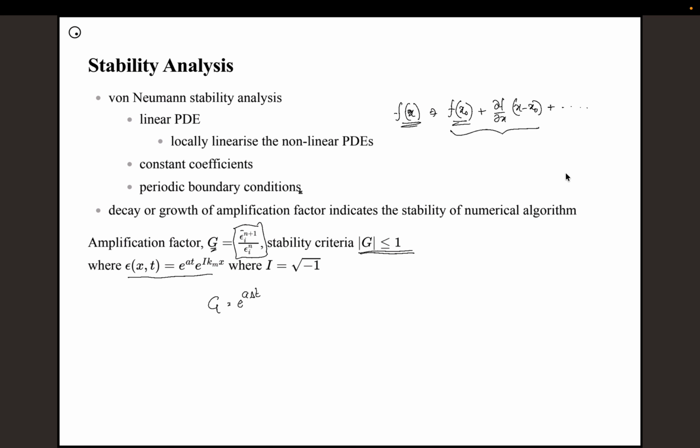And in order to do that, we expanded the series using Fourier series, and we understood that if you are using a consistent scheme and this amplification factor is greater than 1 for at least one of the modes, I mean this km value, for at least one of the wavelengths, then the solution becomes unstable eventually. If you march infinitely, then eventually it becomes unstable.